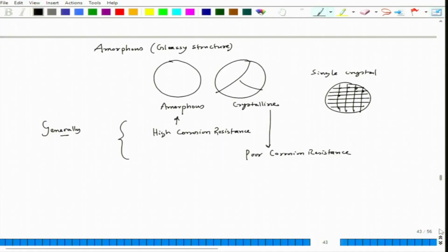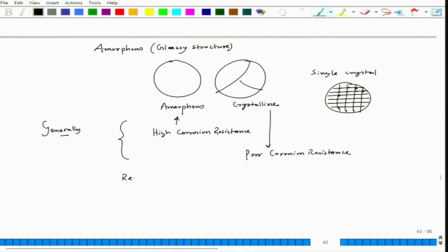There are reasons for this: how these atoms, which would like to be in a regular arrangement, which is the stable state, actually go through a particular transformation where the atoms become random. Okay. And since it is random, grains will not form and it will form a grain-free microstructure. So for our discussion, in a simple fashion, these are the reasons why amorphous phase forms.